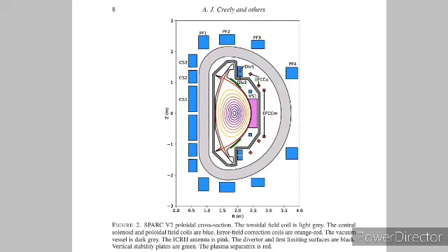The central solenoid and poloidal field coil set will be capable of producing 42 Weber of magnetic flux to initiate and drive the plasma current with a plasma flat top time of 10 seconds, and all systems are being designed to support full power operation for a 10-second flat top.